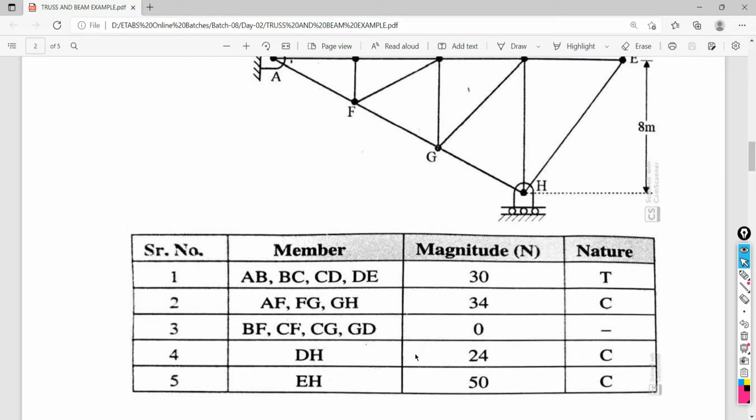So along with this validating exercise, you are getting so many things: how you can divide the frame, what the procedure of making the selection is, how to look at what things are in selection, how to assign the loads, how to assign the releases, so many things. How to see the reactions, how to see the actual forces in the members, how to make the assignments of the loads visible in the view, how to turn this off, how to make the grid lines visible, how to make them invisible. Are you getting it? Hello.